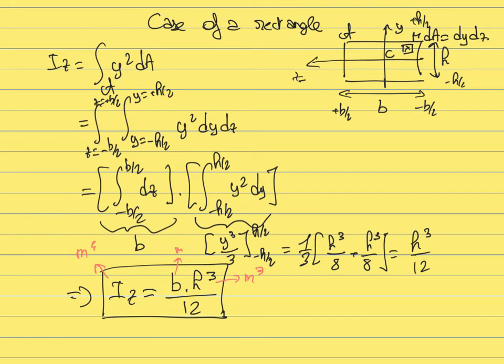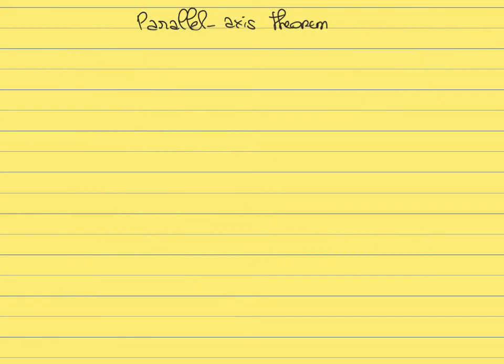When the beam doesn't have a simple rectangular shape, most of the time you still do not have to solve the value of the integral explicitly. Why? Because you can use the parallel axis theorem. The idea of the parallel axis theorem is that if you have a beam that has a complex shape for the cross section, then you can decompose this surface into a collection of smaller subsurfaces, where each of those subsurfaces is a rectangle.